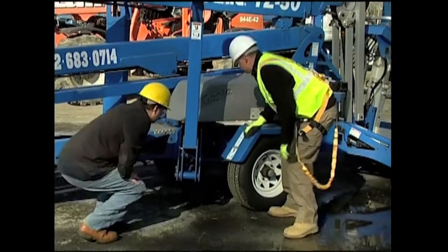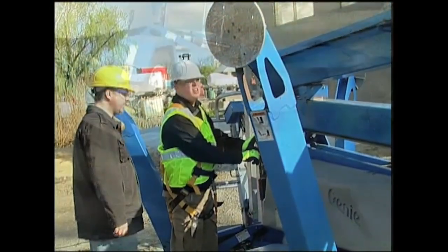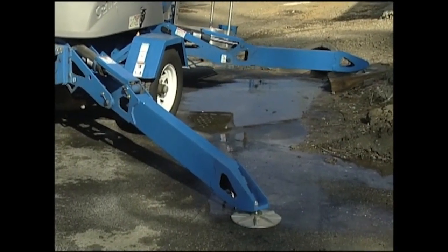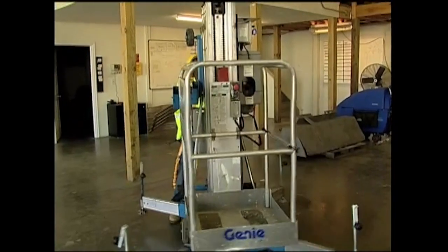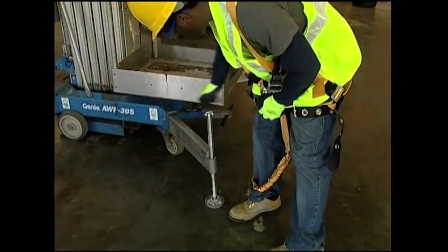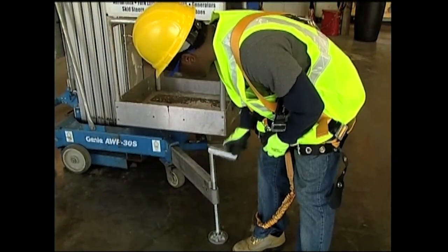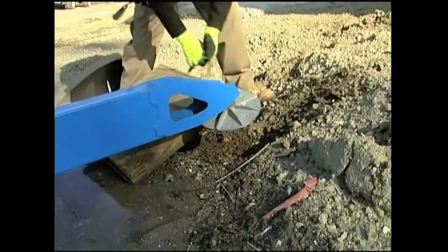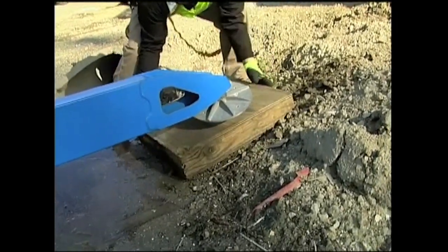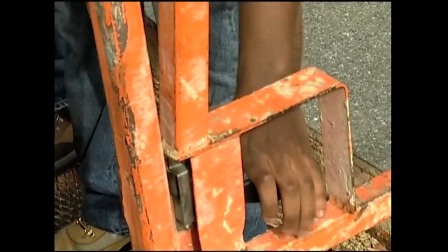Once you have ensured that your aerial lift will operate correctly and that the area where you'll be working is safe, it's time to set up your lift for use. First, position the lift where you want it. If the lift has outriggers or other stabilizers available, position them on a level, solid surface. If you're outdoors, you may need to move some earth or lay down pads to get a proper base. Make sure that the access gates and openings can be closed and locked.